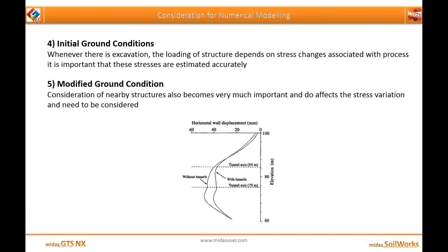So one should always take care of the initial ground or the modified ground condition, as the whole analysis is associated with the stress changes, and to determine accurately the results, the initial stress condition should be properly initialized. So one should take care of that.